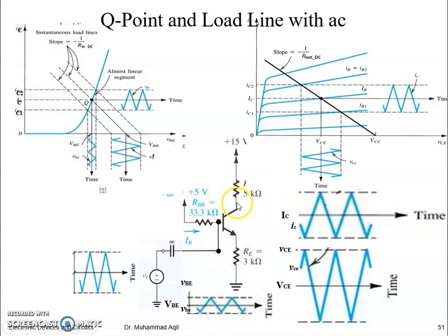So it means if you check here, you will get a DC offset AC signal. But after the capacitor, if you take it with reference to ground, you have zero DC here, and only the AC VCE. So this is our output, where we had given a very low amplitude signal, and we are getting this.